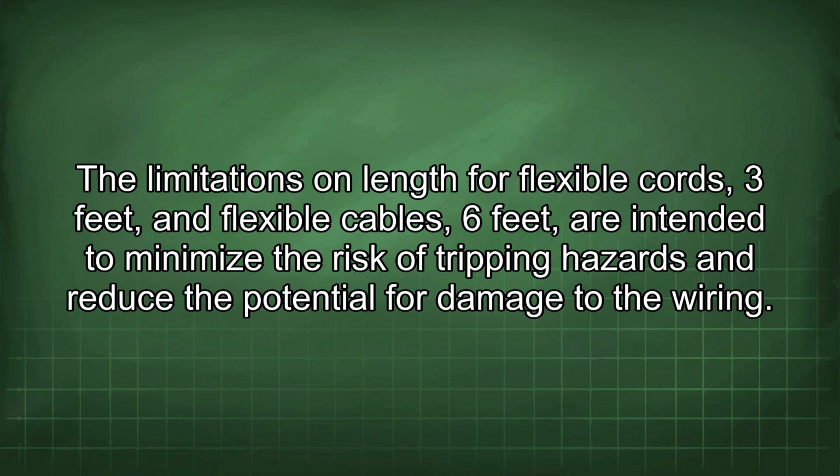The limitations on length for flexible cords, 3 feet, and flexible cables, 6 feet, are intended to minimize the risk of tripping hazards and reduce the potential for damage to the wiring.